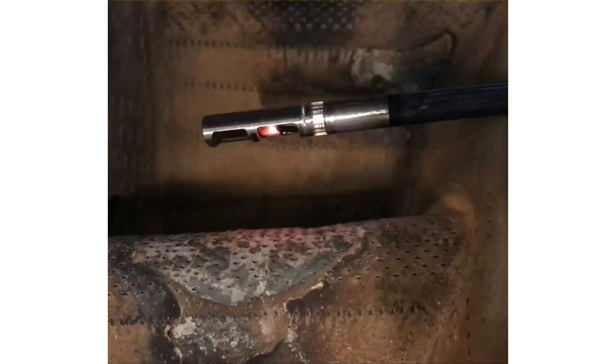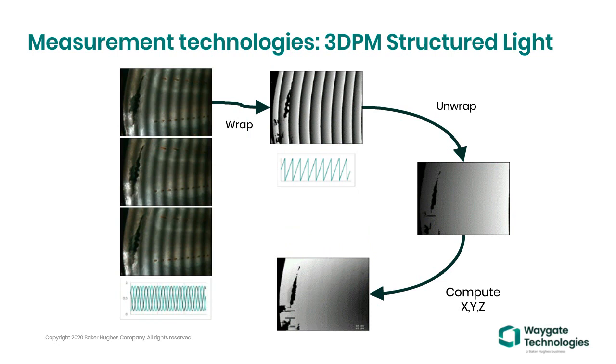What you just saw in the video was two iterations of this sequence. So there are a series of white light images that are captured. In between the white light captures, on the left, there's a group of sinusoidally shifted image patterns that are captured where the LEDs fire and cause this phase shifting image to be captured.